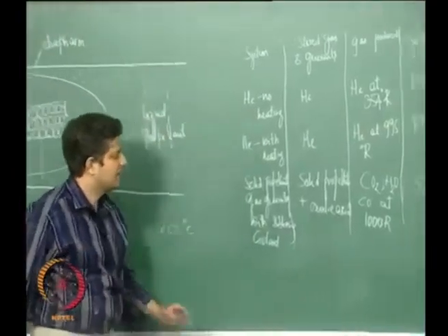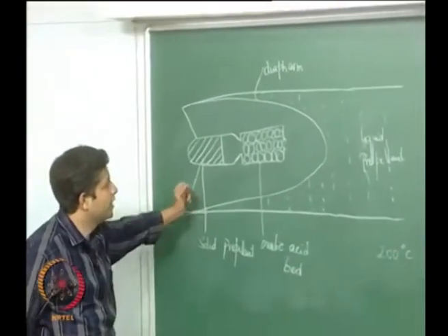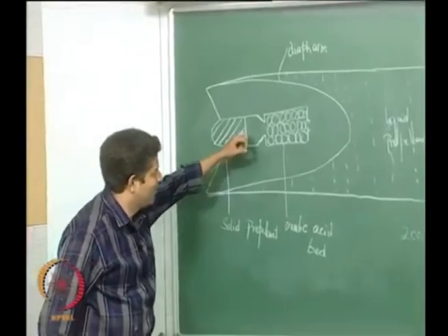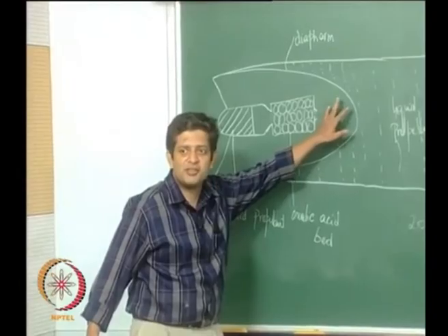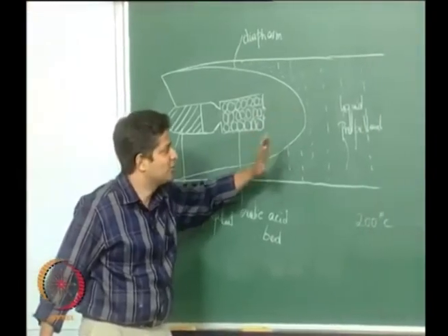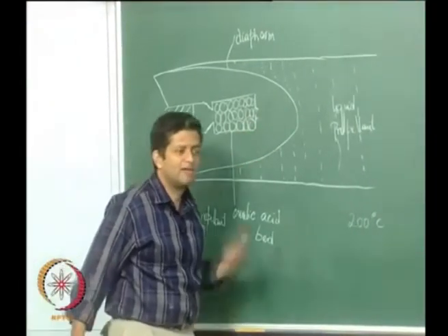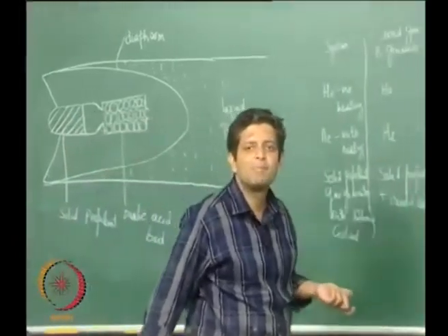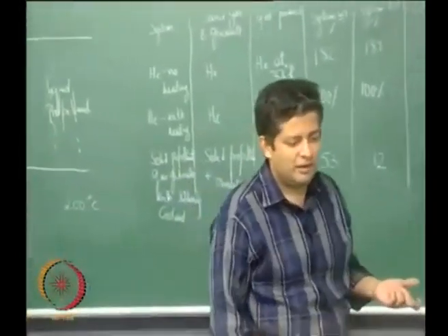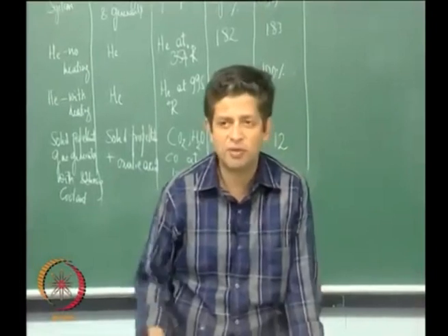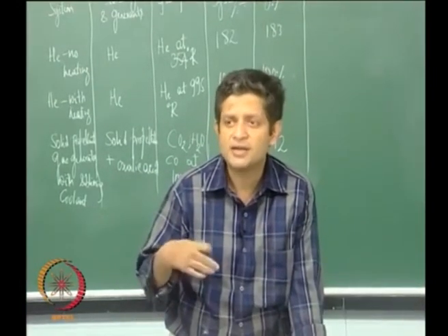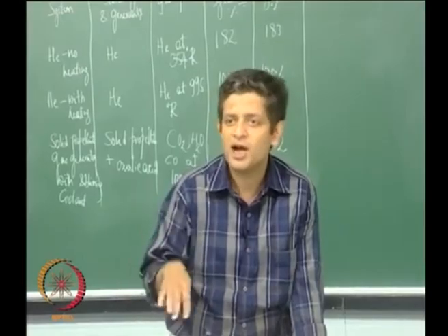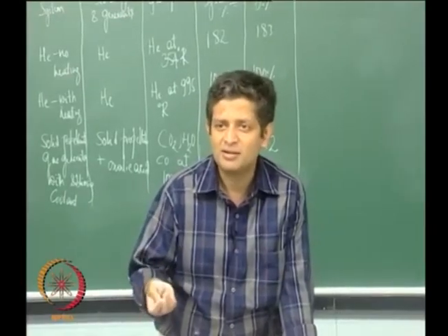But the challenge, as I said here, is you are looking at having very high temperatures here, and at the end of it you should have lower temperatures, right, and you should be able to have a controlled burning. This kind of a system, if you have a solid propellant, is not amenable to start and stop, because you cannot start and stop a solid motor on command.